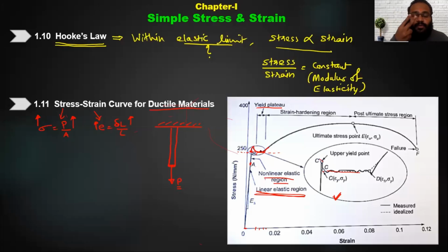बट वो जो एक्स्ट्रा 2 mm तुमने डिफॉर्मेशन क्रिएट किया था after loading beyond the yield point will be permanently there in the material. वो 2 mm कभी regain नहीं कर पाएगा. So that is the importance of that yield point. So in practical applications, we never go beyond yield point.